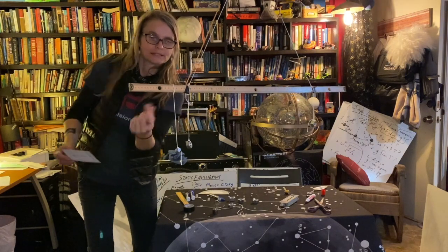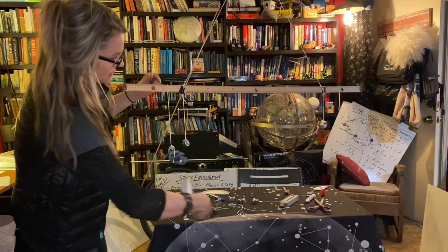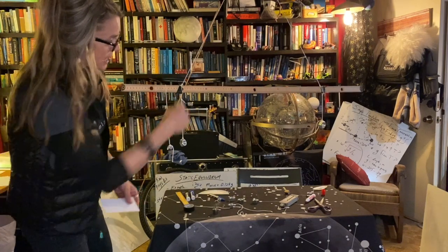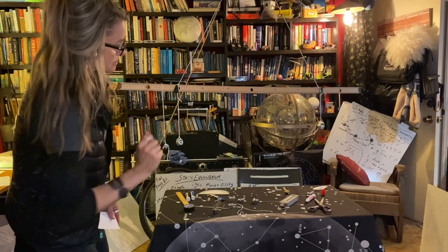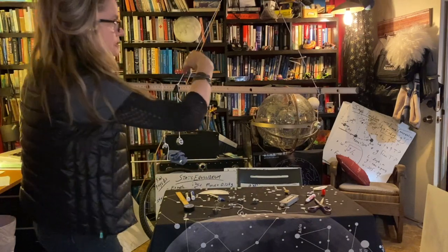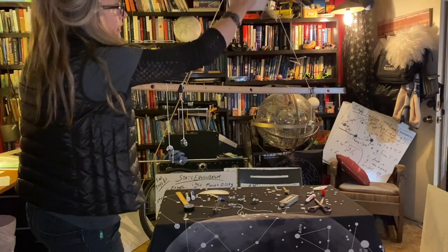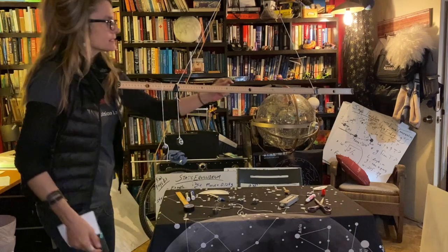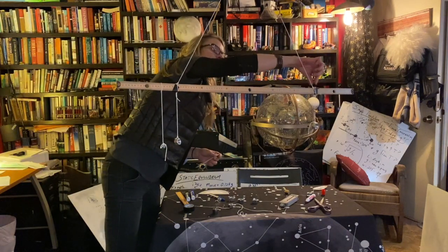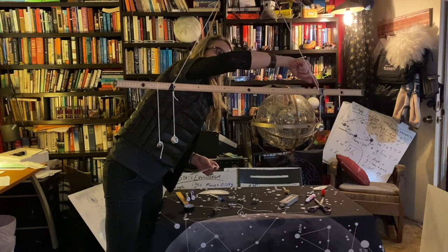So it's going to pull it downward this way. It's pulling down, so it results in a counterclockwise motion. This mass is pulling down, so it will result in a counterclockwise motion. This tension is pulling it up, so this will result in a clockwise motion. And this tension is acting at 30 centimeters from the axis of rotation.